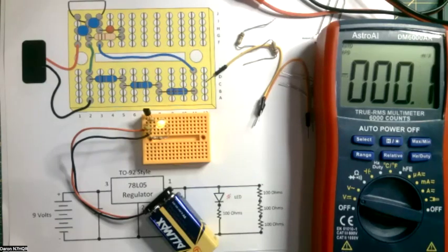Can you explain briefly what the regulator does, why we have a regulator? That's a good question for Joe. All it's doing is dropping an unknown voltage between 6 and 30 volts down to 5 volts so that we can work with a 5-volt circuit. That's my answer. Yep, if we had a 12-volt circuit from our car and we needed 5 volts for what we're doing, this is how we would get there. It's just a built-in regulator that drops the voltage down to 5 volts and limits the current. Okay, thanks.